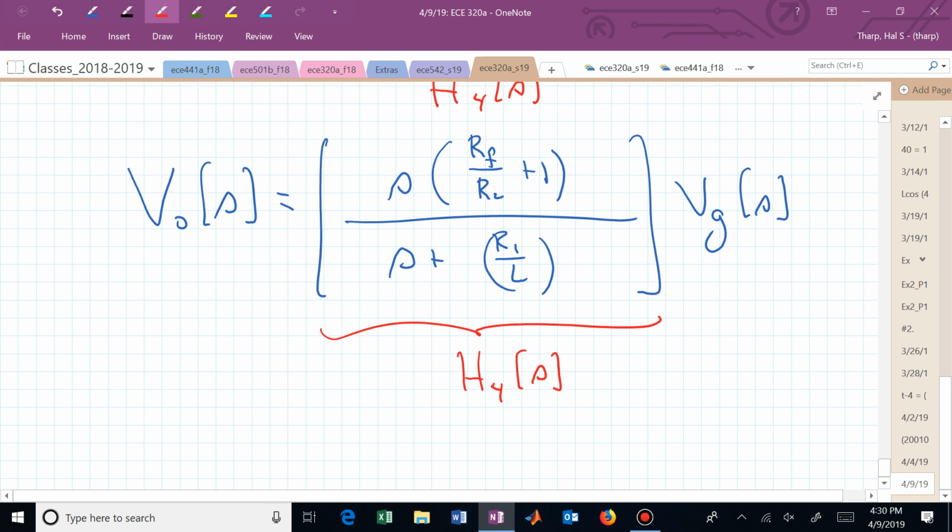you're not hearing much. Then we're coming up, because that's a linear factor, we're coming up how fast? 20 dB per decade. And then what happens? Then we stumble into this pole, and it cancels that slope change that we were coming up, and those are supposed to be equal angles. We add them together, we're flat.